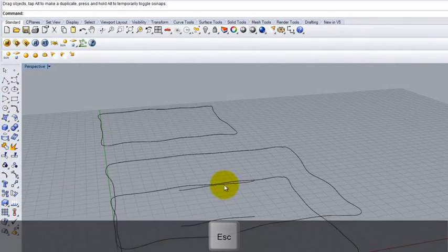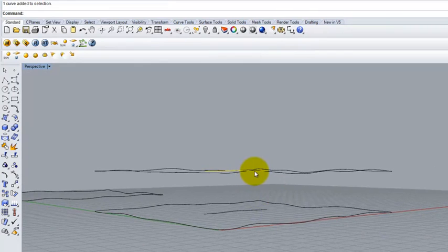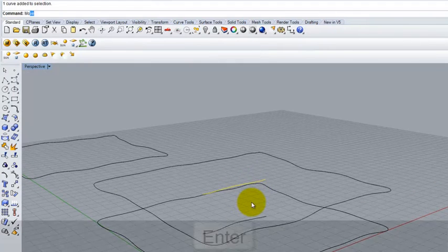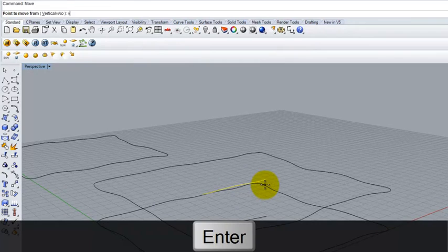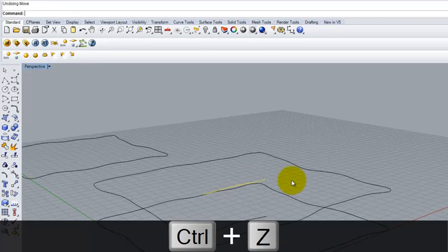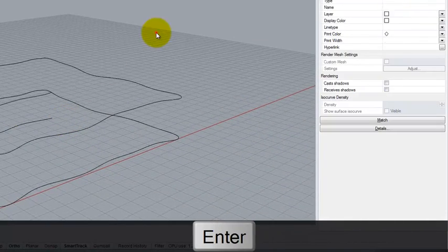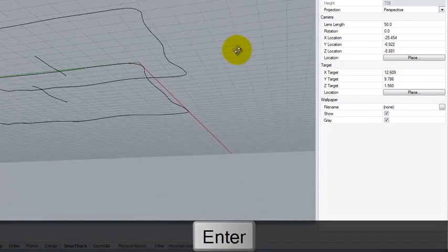Now, I'd like for these to actually be down just, it's not going to be quite level with the surface. I'd like to push them down a little bit. So let me move, and I'll type V for vertical because I'm in the perspective view. We'll go down, I don't know, let's do a ½ inch. Oops, should have been negative ½ inch. I could just drag these. It's just habit to actually type a value. Okay. So if we start to look at this, yeah.